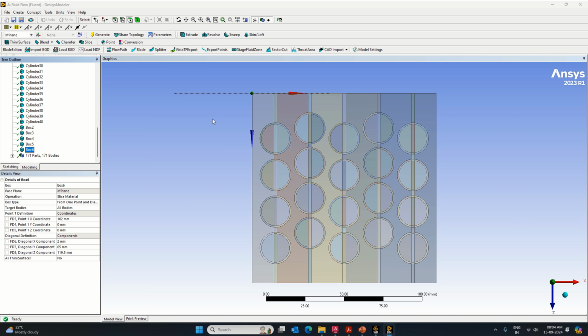So I will select all this center part. Okay, I will select as an entire 3 things, and I will make this unite so as to become a cell. Okay, so the last one. So go to the create, I will go with the boolean operation, make it unite. So the 60 bodies will be unite like a cell. So this is now your cells.